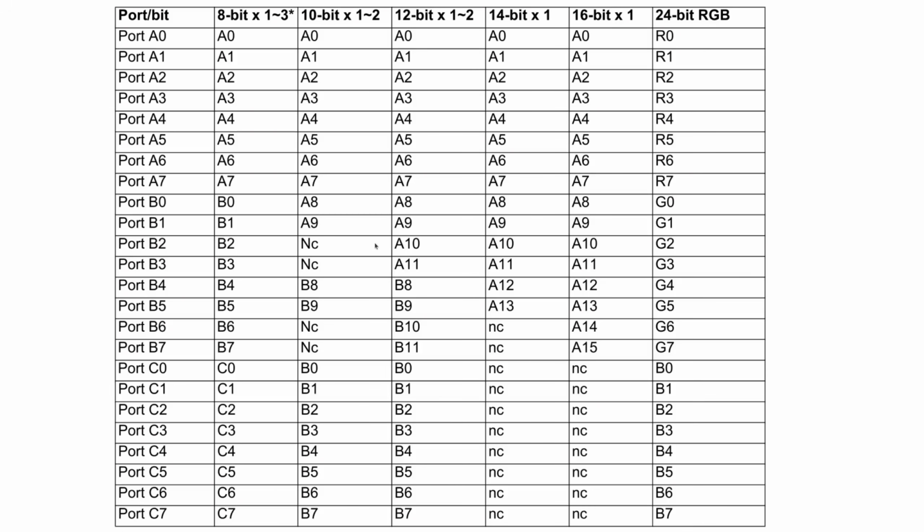Next thing, we take a format. So in 8-bit, A0 through A7, these are the pixel values mapped to A0 through A7 on the port. Now that's a nice 1-to-1, but when you go to 10 bits, A0 maps still to A0, but A9 will map to B1. So this B doesn't necessarily have to map with the corresponding B values.